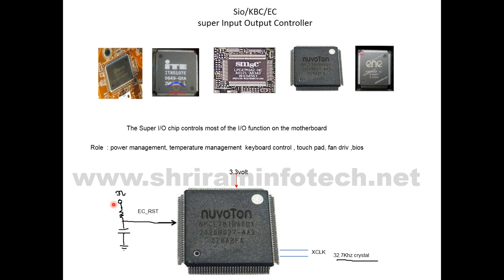Hi friends, today we are going to learn SIO. SIO is a chip which manages the entire system of the computer or the laptop. It manages the power, the temperatures, the fan, then the keyboard, the touchpad, and the lid sensor. So many things are managed, and in a laptop or a desktop, the first component which is going to power on